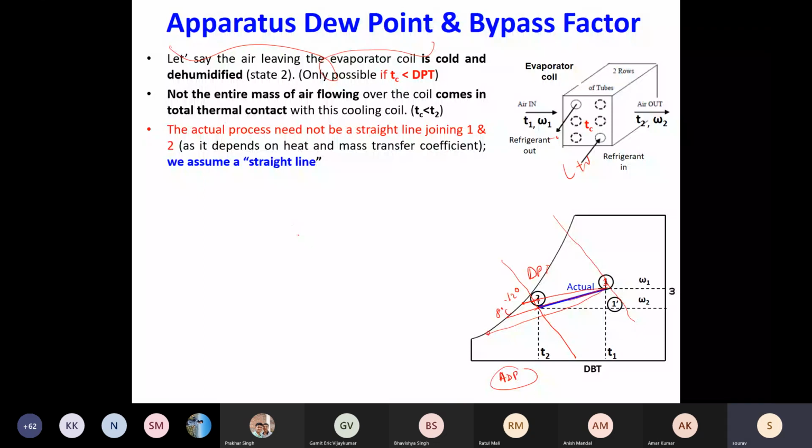And that is exactly what the manufacturer does when you press your dry mode. When you press your dry mode, it lowers the evaporator temperature so that you dehumidify more. There is no smart control over there. You are the control. If you feel that it is now too cold or too dry, you will automatically increase the temperature or move to the comfortable mode. We will change the mode.